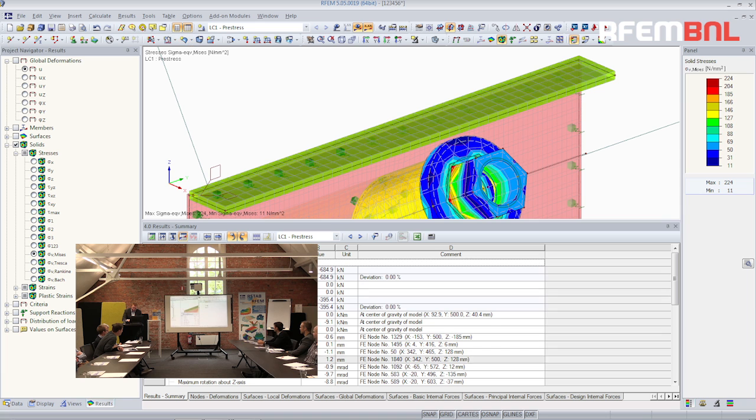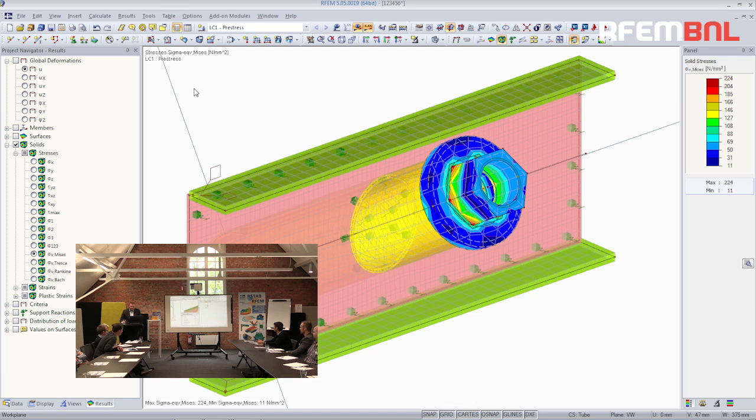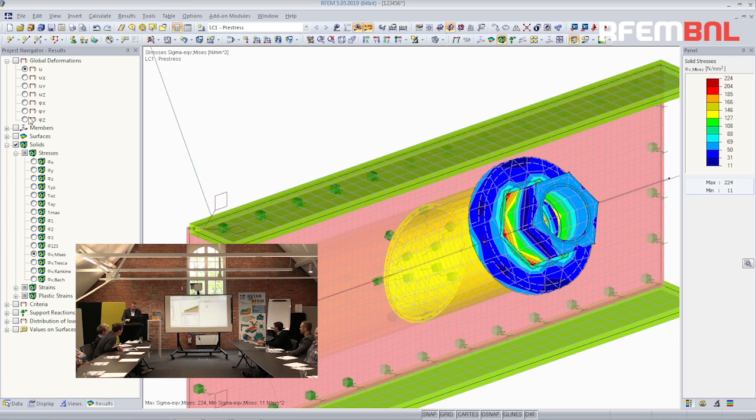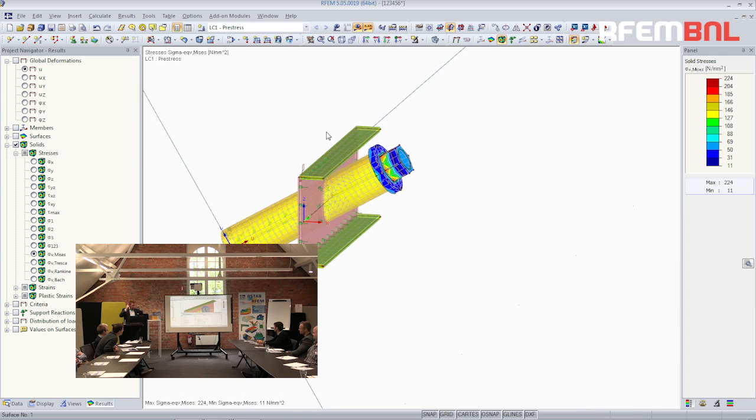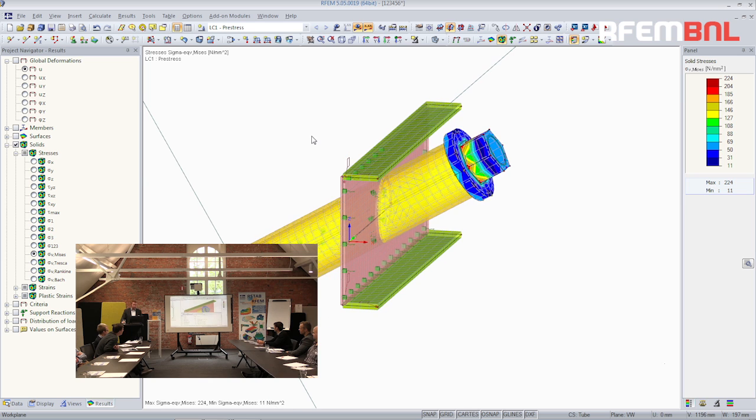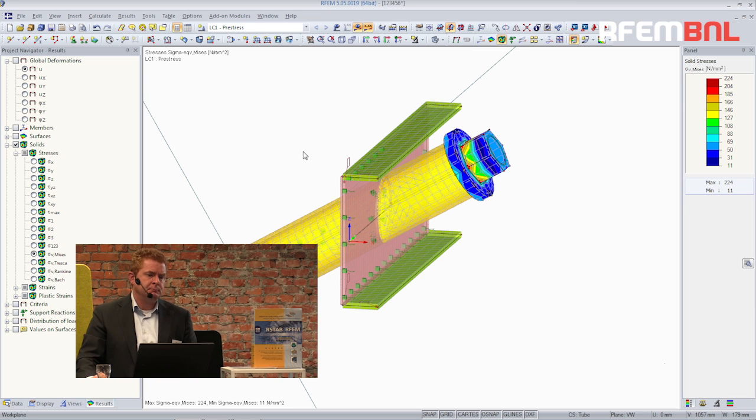I'm improving, see? So, this one. Almost 800, 790. So, if I apply a better mesh here, you will get to 800. But this is always in the back of your mind. Did I apply the correct load? And you should take a look at this summary of loads. Okay, so this is important, I think, when I do this kind of stuff.